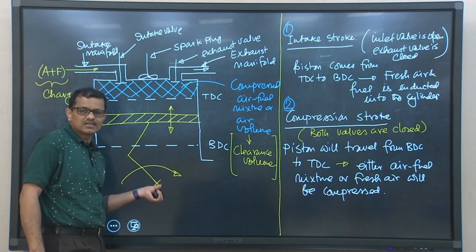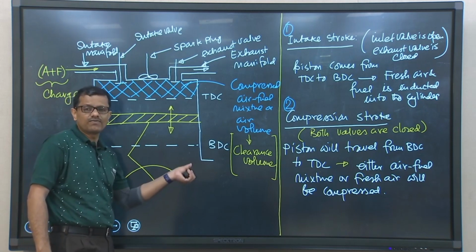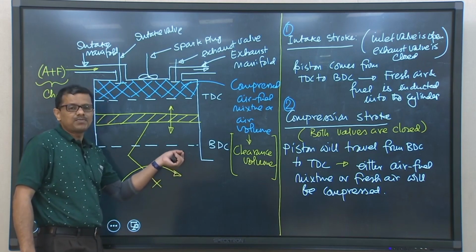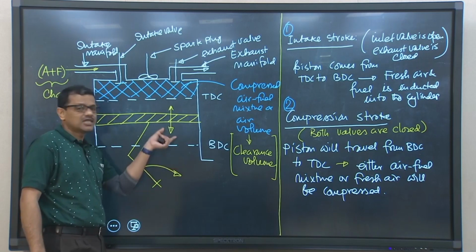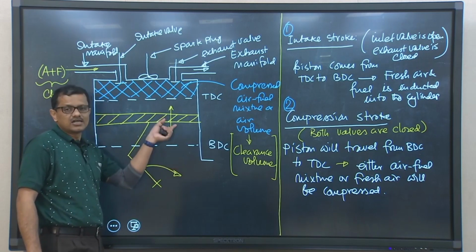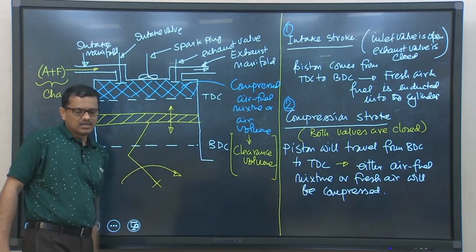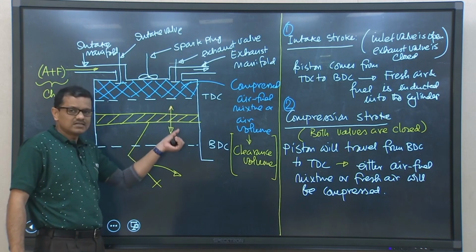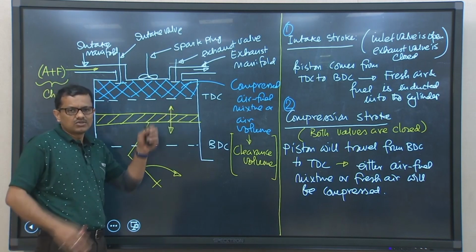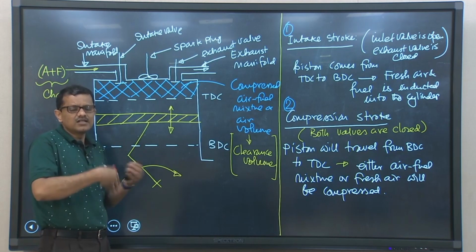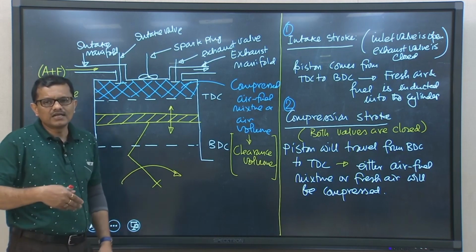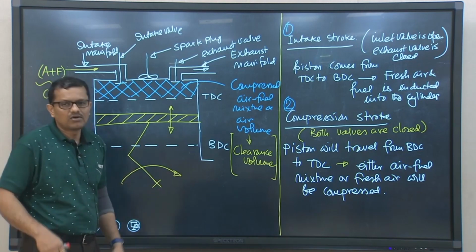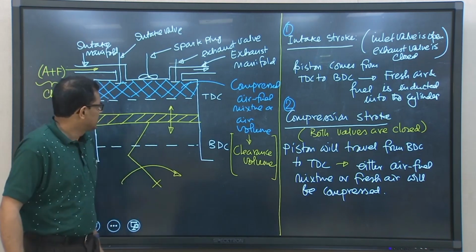The power we are getting at the crankshaft, and this crankshaft is connected to the flywheel. So, a part of that power will be utilized to execute the 3 other idle strokes, and these sequences, intake, compression, power and exhaust, will be repeated to complete several other cycles, and this is the 4-stroke engine.